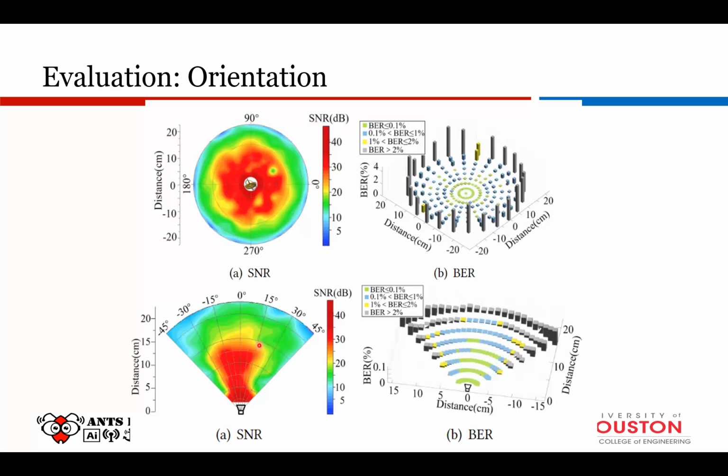Before transmission, the transmitter transmits a chirp, and the receiver listens to this chirp and identifies which is the target receiver. If the chirp covers the whole range of the band, it is the target. Otherwise, it is not. For example, if their frequency is 40 kilohertz to 70 kilohertz, the chirp covers the whole spectrum from 40 to 70, and that's the target receiver.